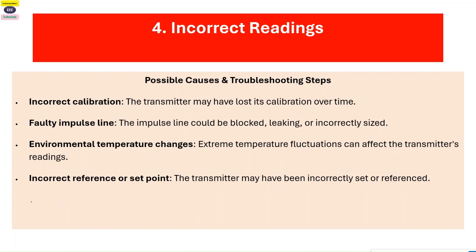Now fourth one is incorrect reference or set point. So you have to also check whether your transmitter is taking reference atmospheric pressure or absolute pressure or vacuum pressure. So you have to check whether it is incorrectly set or correctly referenced.